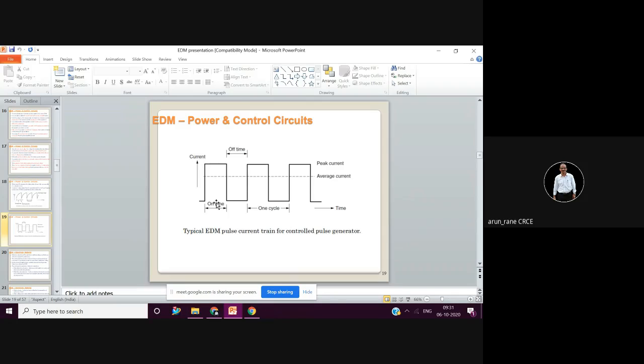So your electrode will keep on cutting the debris instead of cutting the workpiece. Initially, in the beginning, it will cut the workpiece, so chips will be generated. Now, if your flushing is good, then the chips will be moved away. But if the flushing is not good, the chips get trapped between the electrode and workpiece. Then subsequently, your electrode keeps on machining your chips or debris. And this is what is called secondary cutting, which is bad.